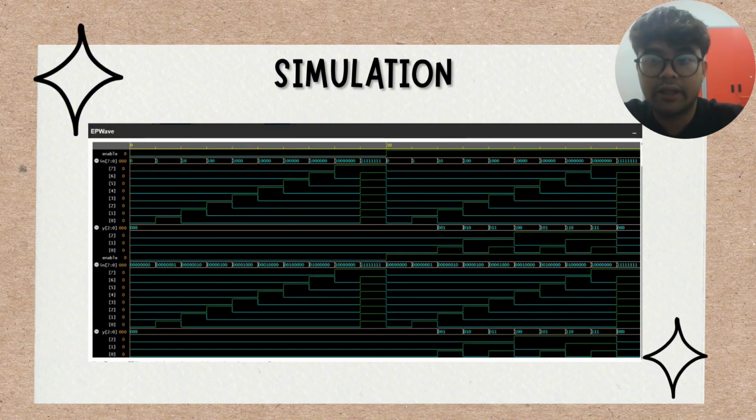Now I will explain about the simulation for question 1 and question 2. For question 1, we choose the 8 to 3 encoder. First, input pattern validation. The waveform shows the 8-bit input in[7:0] being activated in one-hot sequence, 00000001 and 00000010 and so on. This confirms that only one input line is high at any given time, which is the correct operating condition for an 8 to 3 encoder.